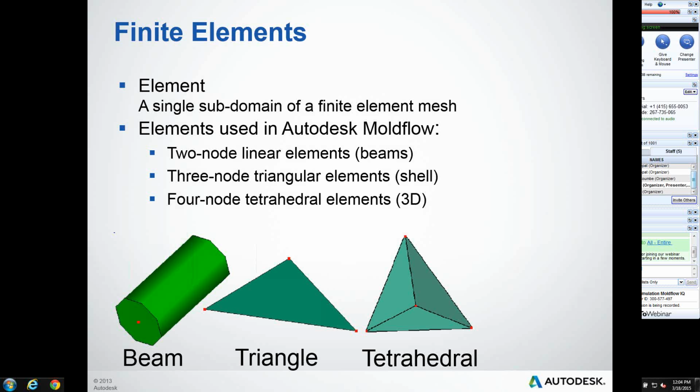It's a volume mesh, a tetrahedral element. Like any good CFD code will tell you, tetrahedrals are usually the best representation of fluid dynamics. So much like any good CFD code, we have fallen in line with the tetrahedral element as the most accurate, most efficient way of calculating fluid inside the volumes we have, which are basically plastic parts.